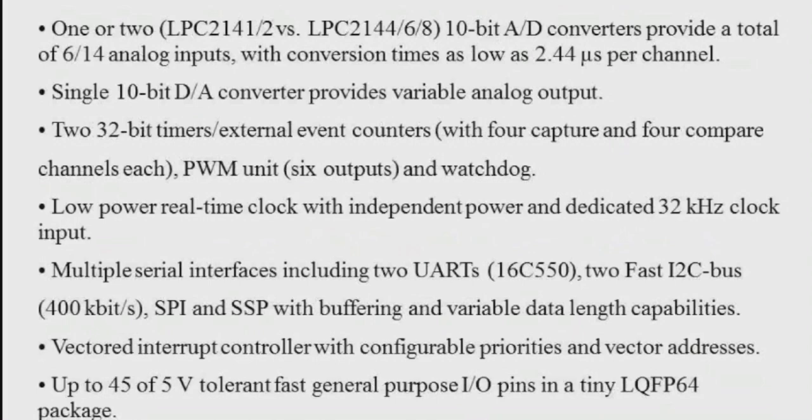It has two 32-bit timers, also external event counters including 4 capture and 4 compare channels each, and also a pulse width modulation unit consisting of 6 outputs and a watchdog. It also has a low power real time clock with independent power and a dedicated 32 kHz clock input.